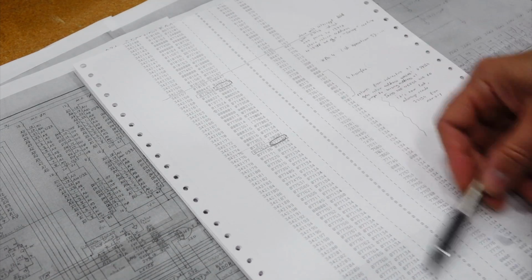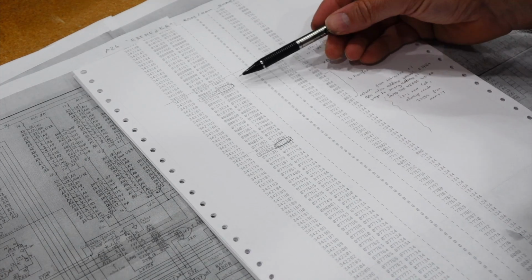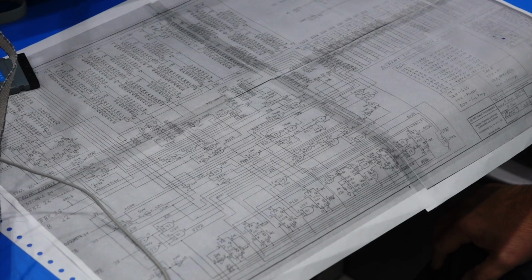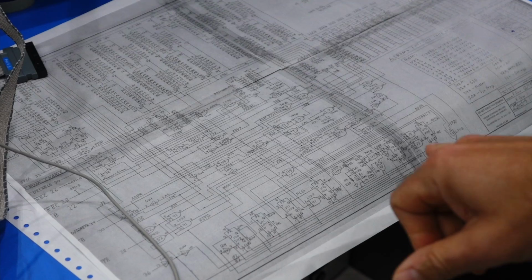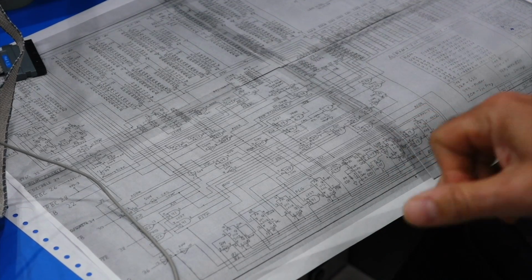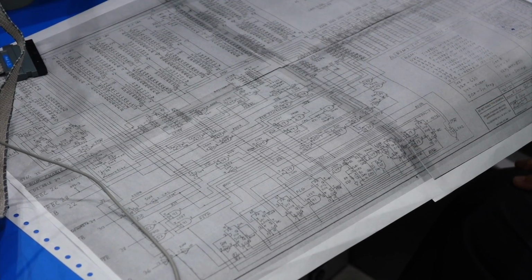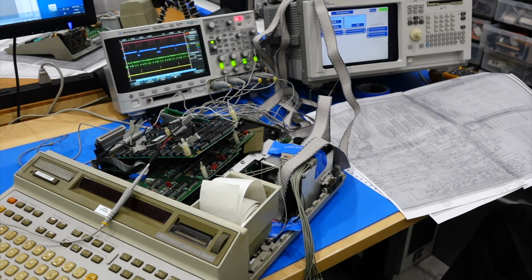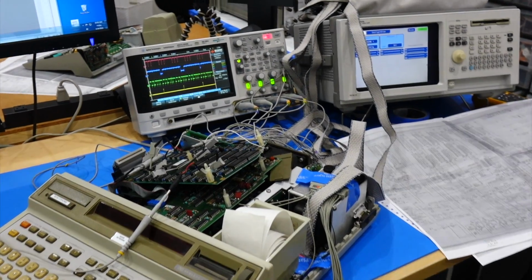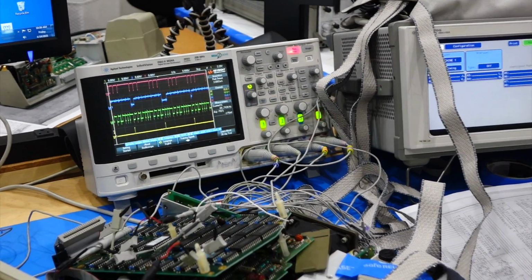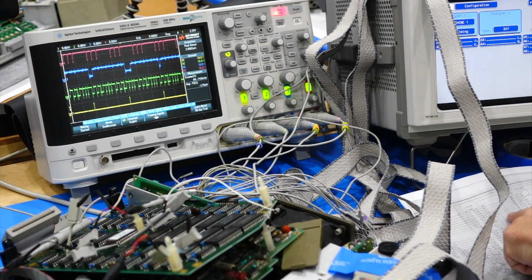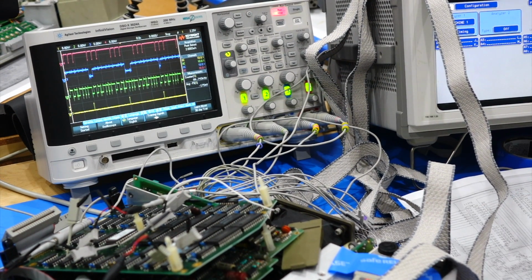From the logic analyzer trace, we suspected a memory refresh problem. But we got stumped by the complicated TTL noodle logic that implements the DRAM controller. We clearly got very different results from our working 9825 that we use as a reference. Both machines showed the same tick signal that starts the refresh cycle on the yellow trace, but the response to the refresh seemed completely different.